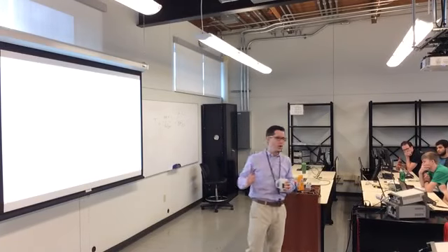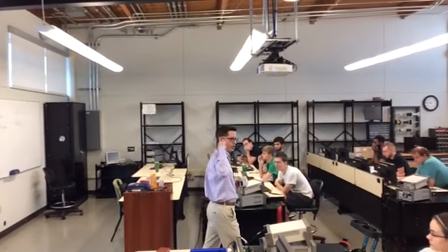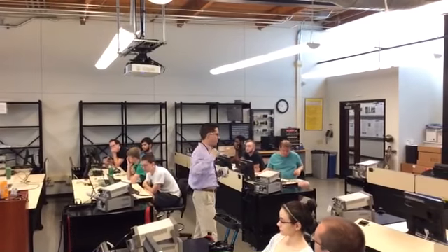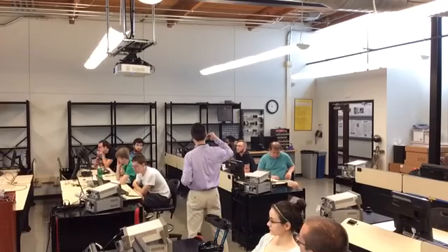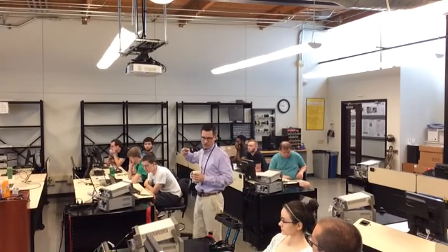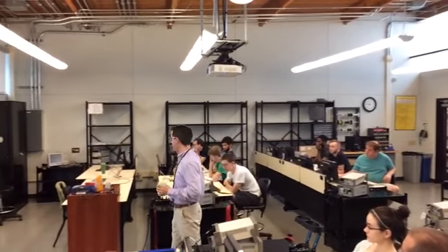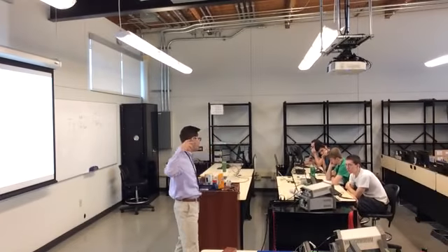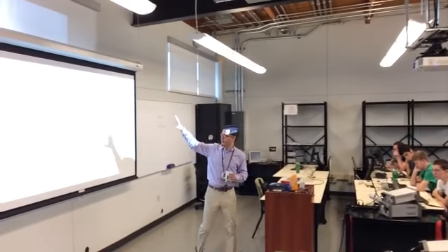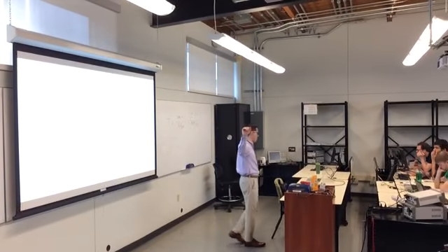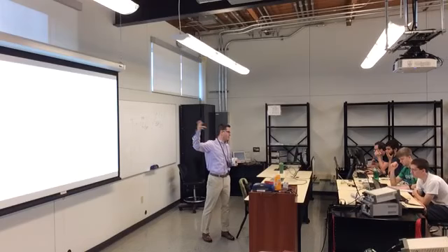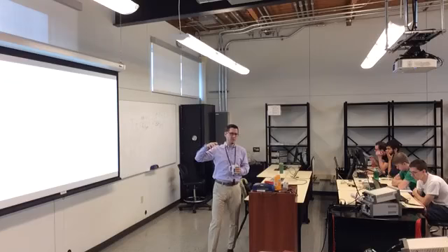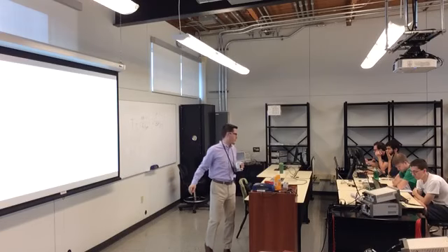All of this stuff you could do with a processor and a GPIO pin, but it would be really, really annoying. You would have to read the pin, catch the interrupt, sit in a busy loop until something was done, and then do it again. And if you remember our system diagram, the processor is way away from the other peripherals. It's better to have this timer do it on its own and give the data to the processor. The processor is also the major energy hog in a system. If you can shut it down, then you can have your other peripherals do its work.